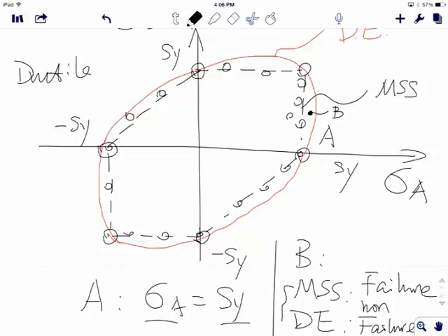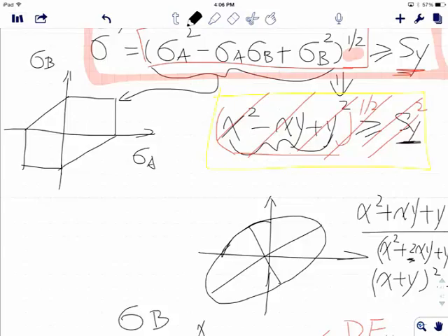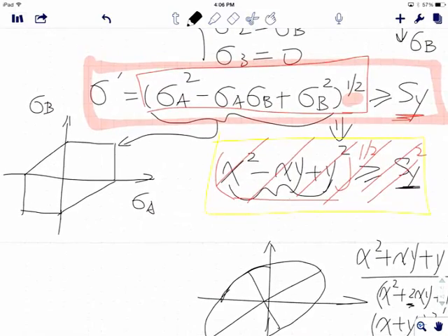So back to the fundamental, it depends on whether you want to be conservative or you want to be aggressive, right? Make sense? Yes? All right, but since maximum shear stress is very hard to predict, and I don't think the finite element can tell you the maximum shear stress, whatever, different case. But finite element can easily tell you the von Mises stress, which is a,